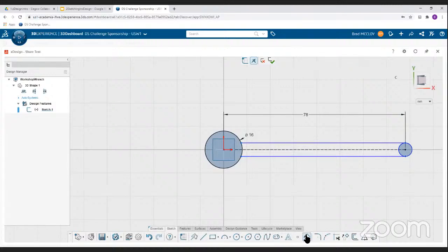That's kind of how we talk about how we build on CAD. So let's make that handle a fixed width, and based on the wrench I saw, the tiny little wrench, we'll start dimensioning that. So I clicked on the dimension tool. You can see it automatically defaulted to dimensioning this line, which we don't really care about, but it's still floating, so it's not fully done yet.